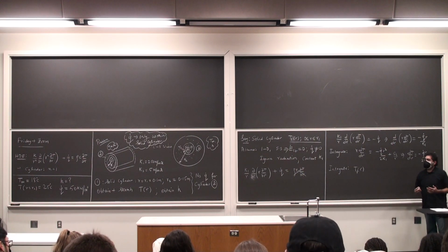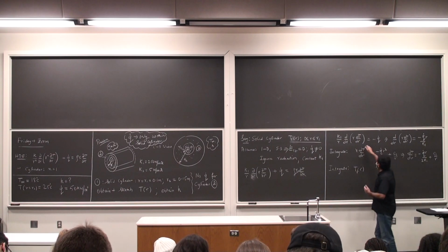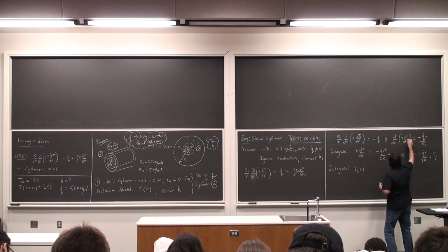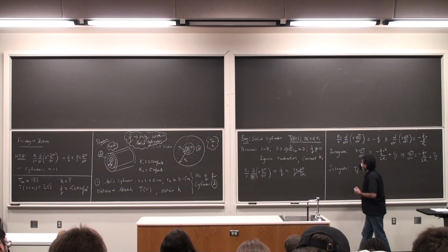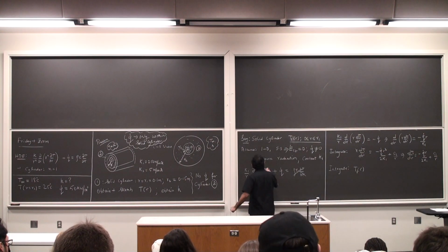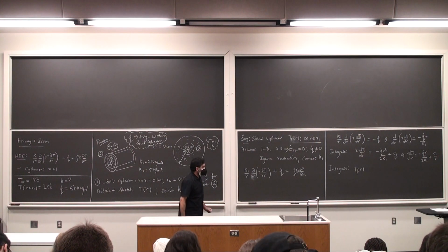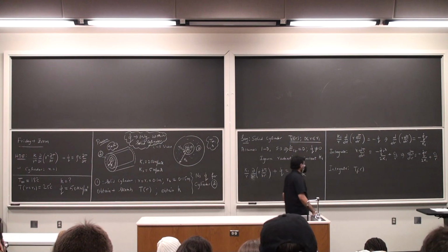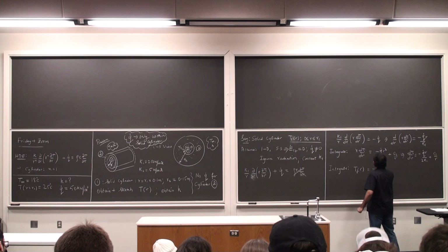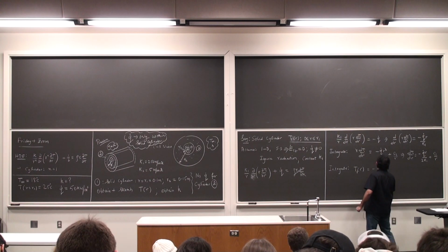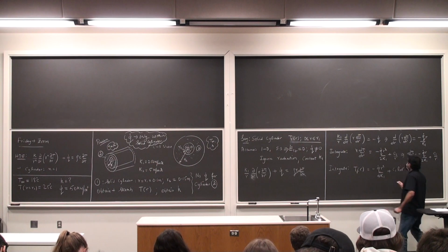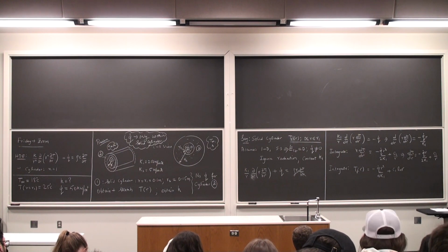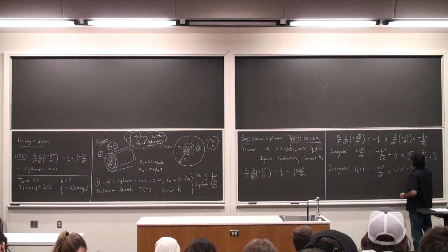Since I call it T1, I'm going to write the subscript T1 everywhere, so pardon me on that. So T1 of r I end up getting as the following: minus Q dot r squared by 4K1, plus C1 times natural logarithm of r, plus C2.